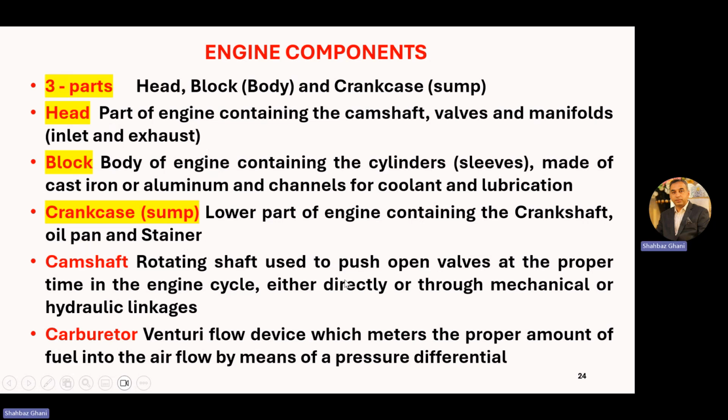They are specifically designed, with a specific shape, a cam lobe and follower arrangement, which opens the valves at the required time in a stroke. They can act either directly or through mechanical or hydraulic linkages.